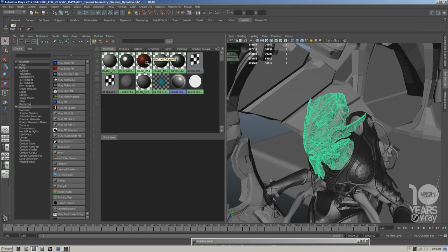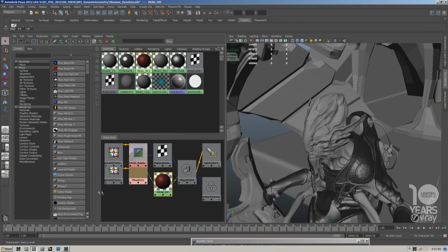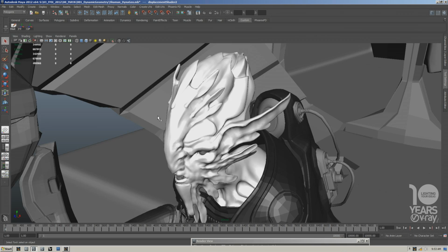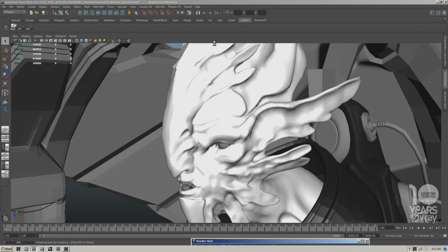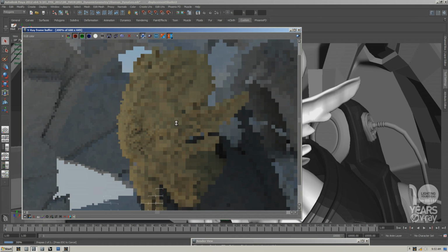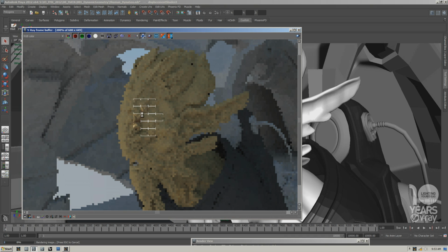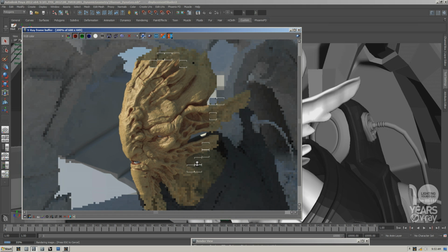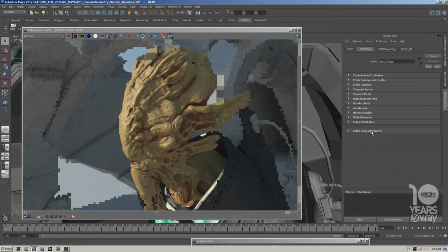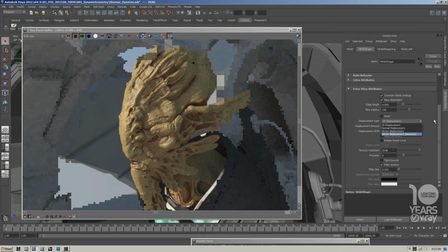So let's take a look at displacement renders with V-Ray. I have a material with the displacement already applied to it. I'll just use it for the head of my character and click render. And you can clearly see that with no delay whatsoever, we get really detailed displacement. I'm actually not using bump maps, no tricks, only displacement. I have ambient occlusion to show you the cavities, but that's it. Basically, using 2D vector displacement is possible in V-Ray, so you can render vector displacement. You can render 32-bit displacement maps, which can be created from ZBrush, Mudbox, or other applications.